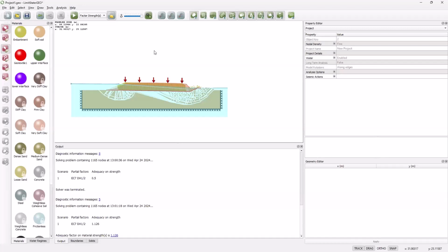And the second question is, would you include a geogrid in a slope stability analysis? So if we've got a platform that has a slope at one of its edges, if I'm reading that question right, then you can put reinforcement in at many different levels. You don't just model one in the software. You can put them in any way you like. So if you've got an extended slope and you want to have reinforcement up the slope, then that can be inserted.